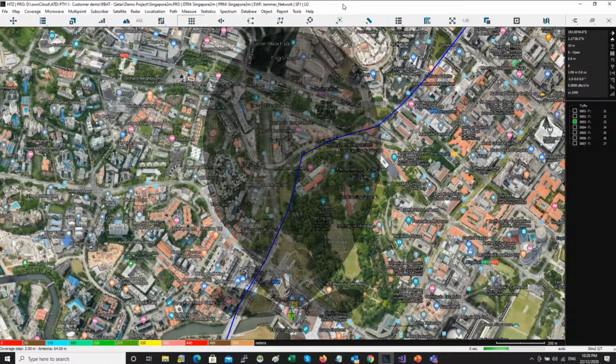And then out of these different heights, it will tell you what is the minimum height with the signal exceeding negative 50 dBm. So in fact, it's the lowest possible jamming height. So if the drone flies higher, you have more chance that you're going to jam it.